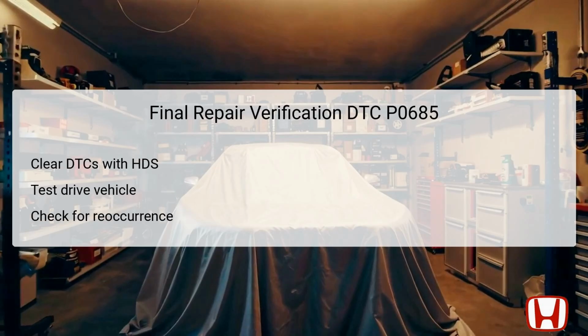and the AF sensor. After completing all repairs related to DTC P0685, it's essential to verify the effectiveness of those repairs. Start by clearing any DTCs in the system using the HDS to ensure that no stored errors impede the vehicle's diagnostics. Follow this by conducting a test drive under various conditions to allow the system to assess engine performance accurately. After the test drive, check once more with the HDS for any reoccurrence of DTC P0685 or other related codes. If the DTC does not return, it indicates a successful resolution of the issue, confirming that the components and connections have been properly restored to operational status.